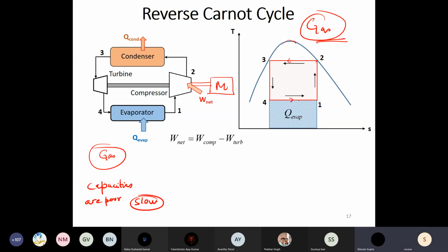Then you can say that isobaric process and isothermal processes are the same. So I can have a heat exchanger where, let's say, the pressure drop because of the friction within the tubes is negligible. So why can we assume this process to be isobaric from 2 to 3 in case of a heat exchanger? Let's say you have any heat exchanger.